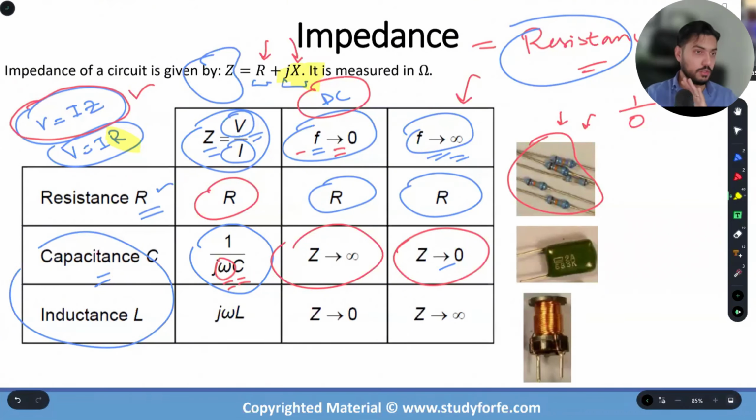All you need to remember over here, whether you're preparing for the FE electrical or PE Power, you don't actually even need to memorize any of this, is to pay attention to where the omega is appearing. Okay. And if you're just starting out with your review of impedance, the crucial point is that the omega is appearing in the denominator. So from a mathematical standpoint, as we increase the frequency, this value actually decreases. Okay. And the frequency is at its lowest when we have a DC. So the frequency is 0. Impedance will basically be infinite.